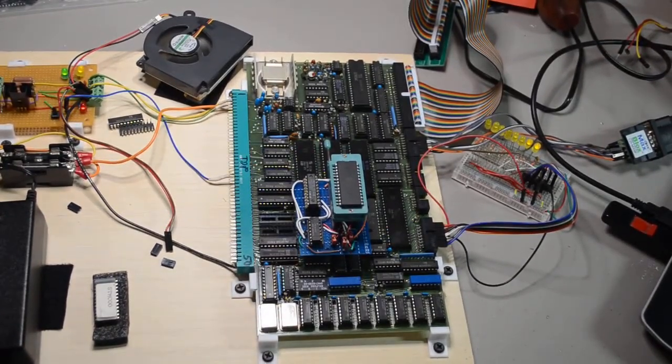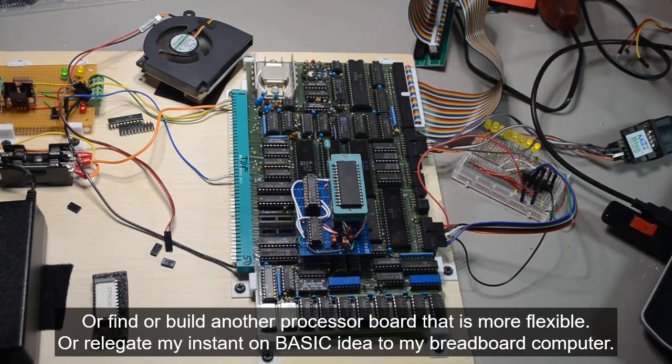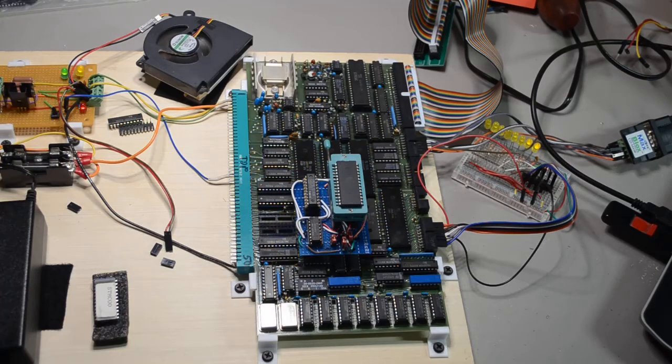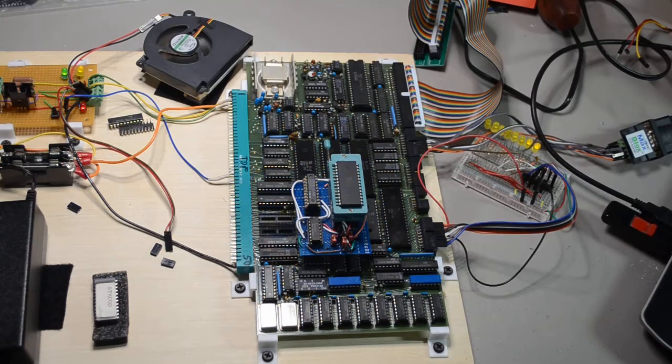So I'm thinking I'm going to have to just take the daughter board back off and work within the limits built into this thing. Now, I need to look and see if I can compress all of this software that I've got into this down into 8K. If I can, that would make this work a lot better. I'd still have to do the trace cutting and the bodge wire installation.